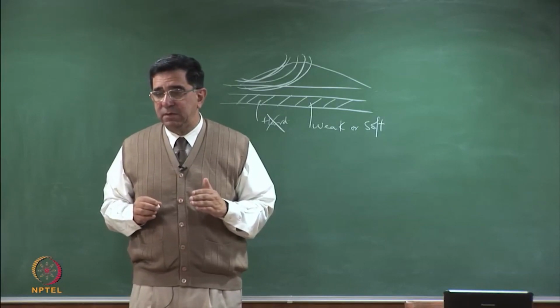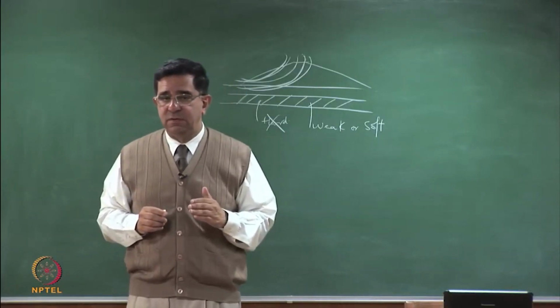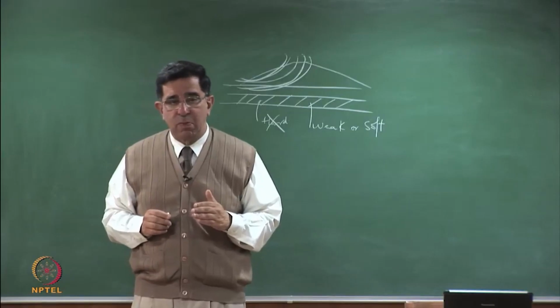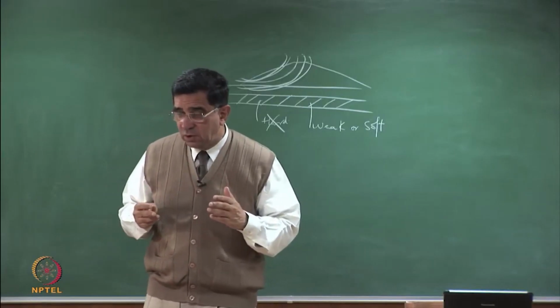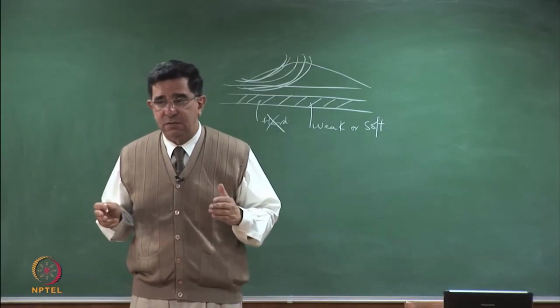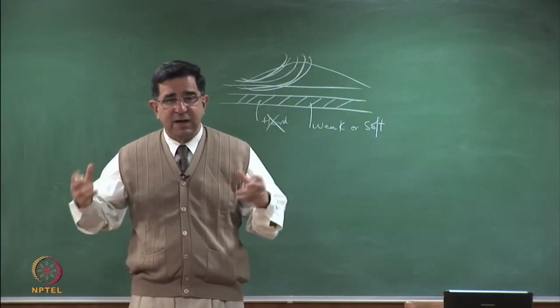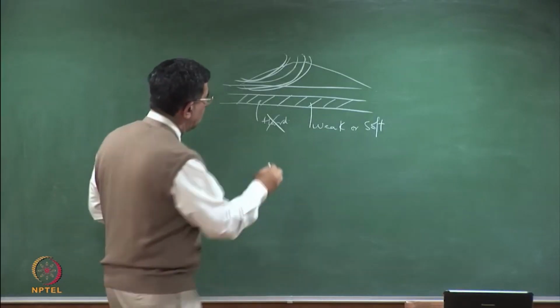In dams and embankments, when do you have to check for straight line failure surfaces? In zone dams, you have a clay core and you have a shell. Which is the weakest zone? In a zone dam, the shell is made of sand and gravel, and the core is made of clay.